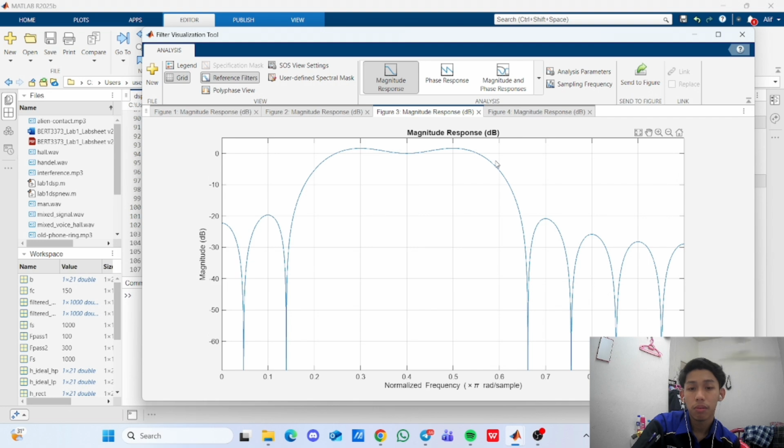In the graph, low frequency signals are allowed to pass with little or no attenuation, while high frequency signals are strongly reduced after the cut-off frequency. The second one is the high pass filter. The low frequency signals are attenuated, and once the frequency passes the cut-off point, high frequency signals are allowed to pass. This filter is useful when low frequency components or interference need to be removed.